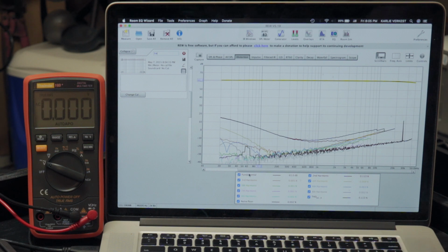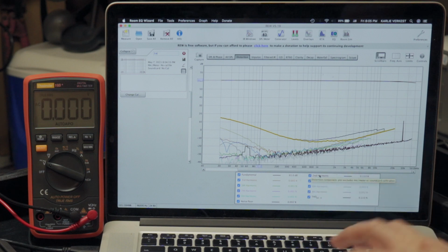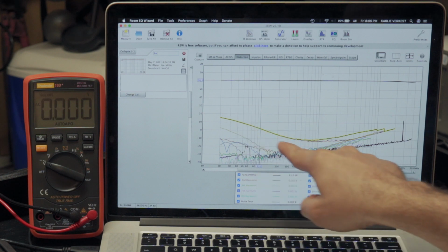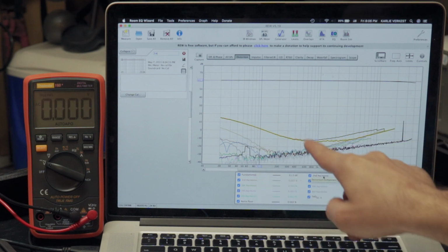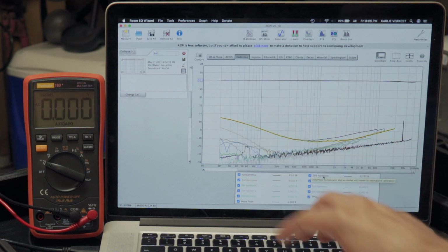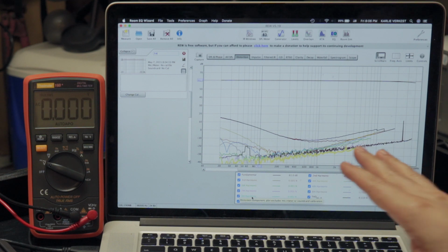And here's our second harmonic. You can see it's dominant here. Now you can see the total: when you add up all of your distortions, you get the total harmonic distortion, and the black line there is the total. The red line here is our second harmonic, right there. And then right on up, here's third, fourth, fifth. You can scroll through all of them and see what they're contributing to the total harmonic distortion that you're getting, right?